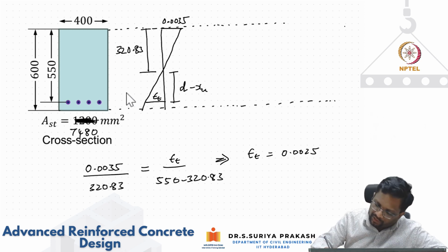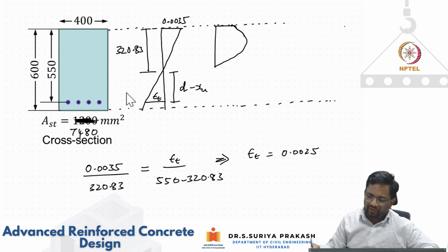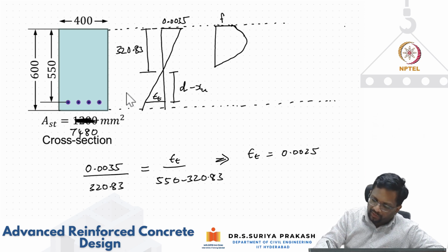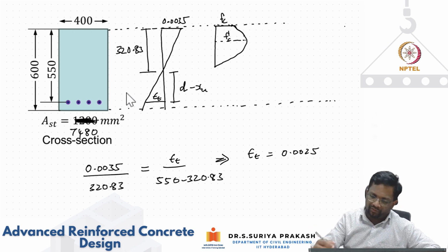The stress distribution in the concrete is going to follow a parabolic curve. It is going to be a low value, then go up like this, and then go like this. So this is the stress distribution from the parabolic Hognestad model. This is going to be some fc, and your f'c will be somewhere here. When you integrate all of them, that is difficult.